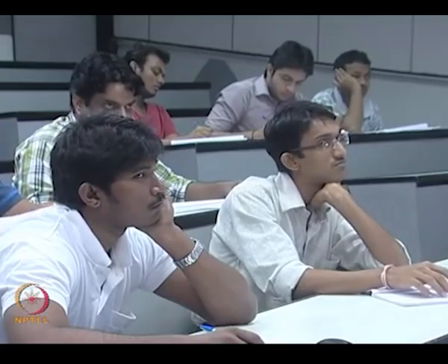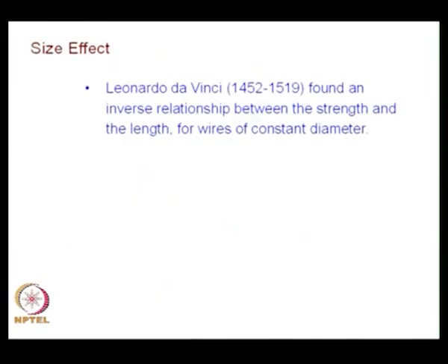If you look at its yield strength, it is something like 220 MPa or so, its ultimate tensile strength would be something like 320 or 400, depends on the material composition. That is all in terms of megapascal, whereas theoretical strength is in terms of gigapascal. That means the theoretical strength calculations are way off. Why is this so? This is a puzzle. People wanted to resolve this puzzle for a very long time, and we will look at what are the kind of issues.